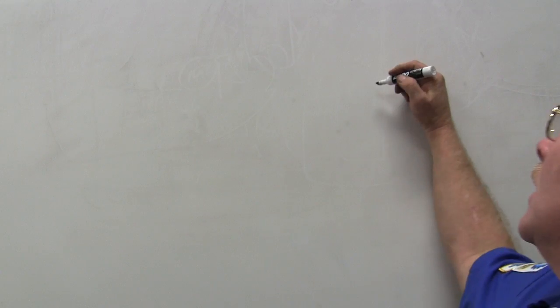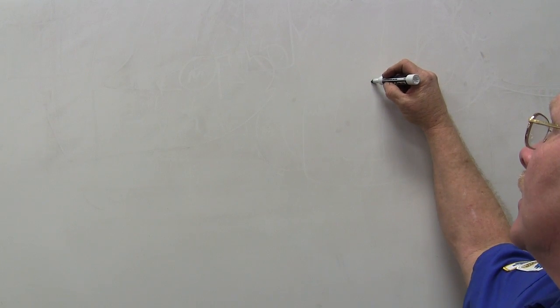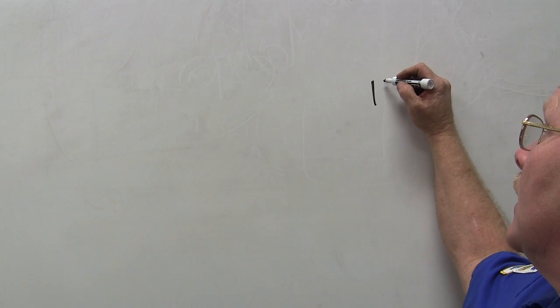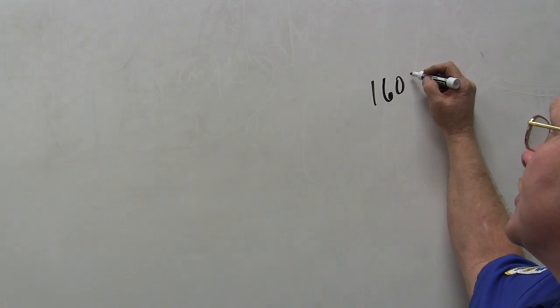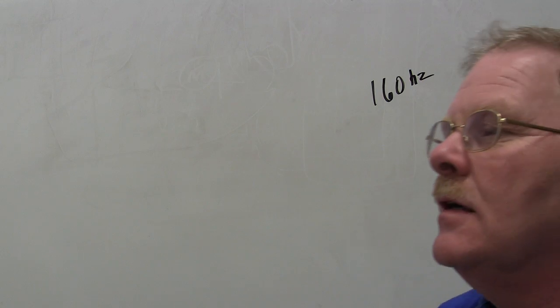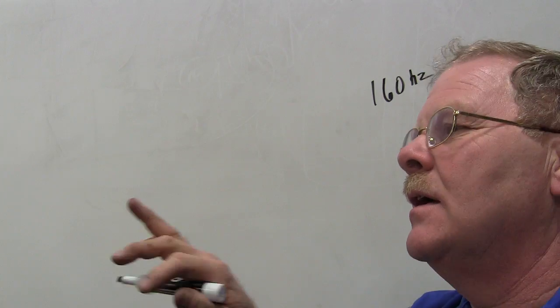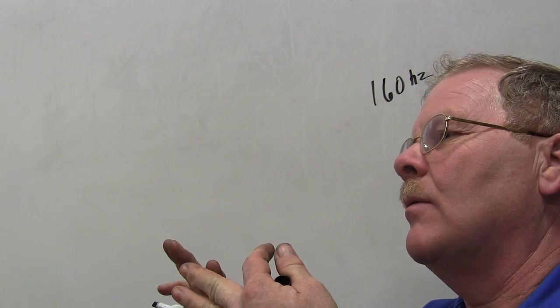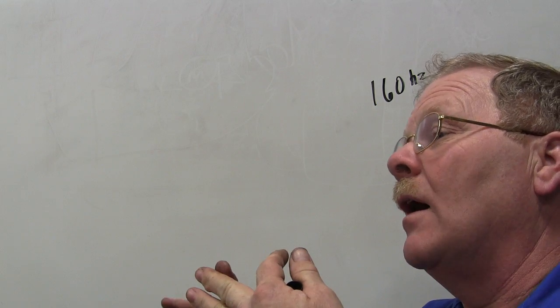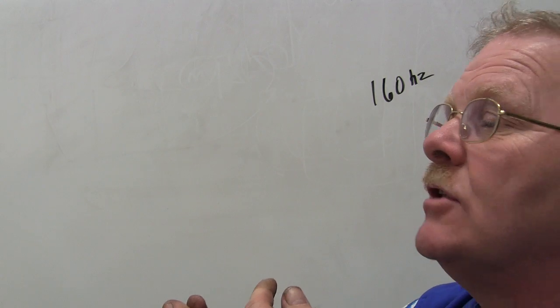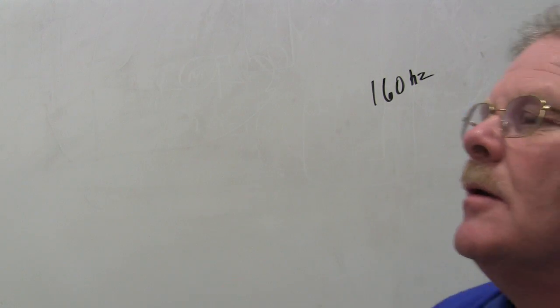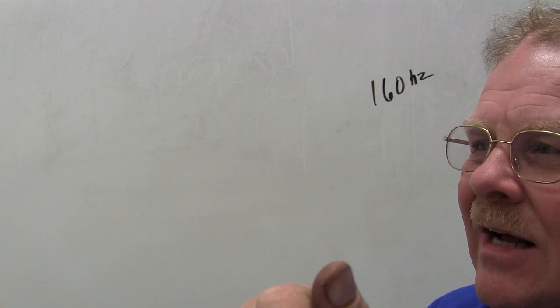All right, we've got this here. 160 hertz approximately is equal to sea level on a sensor like the Bronco uses. Got 3 wires there. You've got an orange wire, a green wire, and a black wire. Okay, the green wire, when the engine's not running, when you first switch it on, is your barometric pressure. The mass airflow sensor calculates that too.